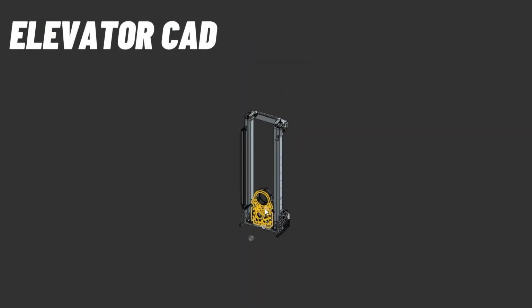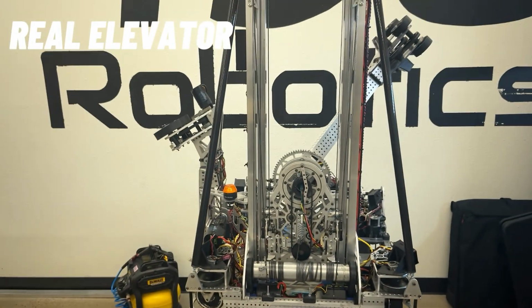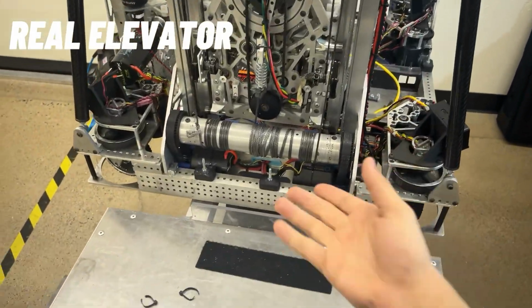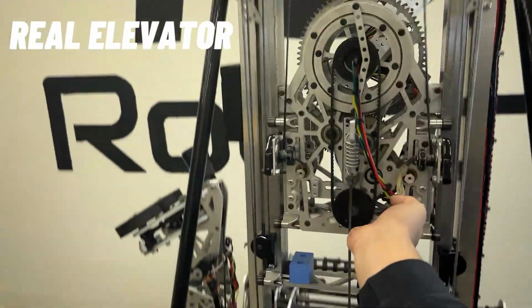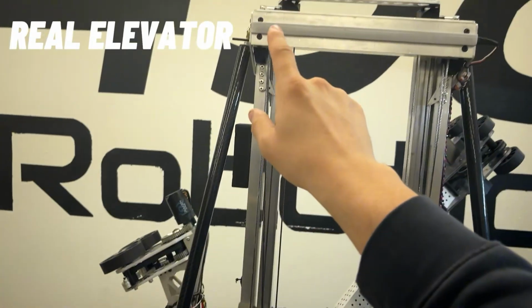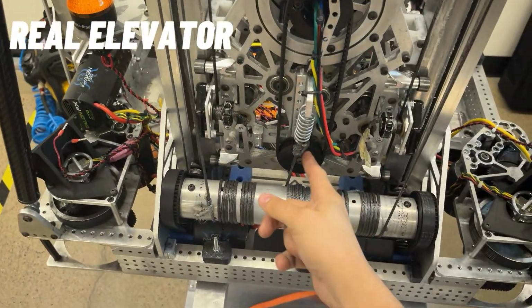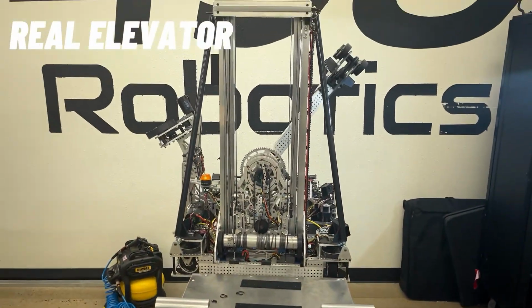The elevator. We chose a 2-stage continuous rope-driven elevator to maintain consistent tension and achieve consistent controlled vertical travel. A rotating tube at the base actively removes slack, pulling the final stage upward for a smooth controlled extension. By integrating hard stops directly into the pulleys, we keep the system compact, and the rope runs along the bottom and the top of each stage. There are also dual ratcheting tensioners and a spring maintaining consistent tension and eliminating slack throughout travel.